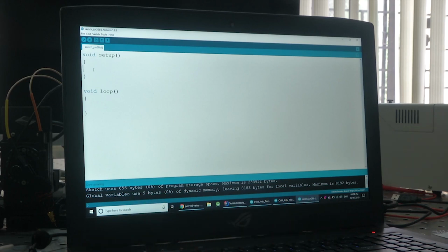Okay, so in this experiment I will be connecting a potentiometer to analog pin A0. I told you earlier that there are 16 analog pins, and we call the digital pins from 0 to 53. There are 54 digital pins, so they will be named 0, 1, 2, 3 like that. We already declared them like pinMode 13, etc. When it comes to calling the name of analog pins, we name them A0, A1 up to A15. There are 16 analog pins, so A0 to A15 makes 16 pins.